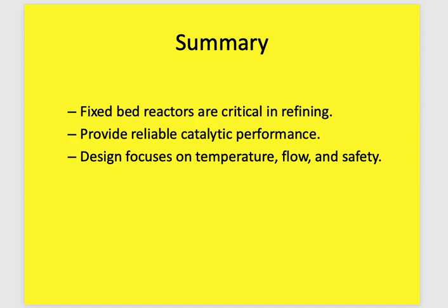So the summary of this type of reactor: fixed bed reactors are critical in the refinery or in the oil industry, providing reliable catalytic performance, with design focus on temperature, flow, and safety. It seems to be so simple in the design, but it is very critical when you survey the parameters. You have to follow up the conversion strictly and evaluate this catalyst from time to time to calculate the weight average bed temperature, or the liquid hourly space